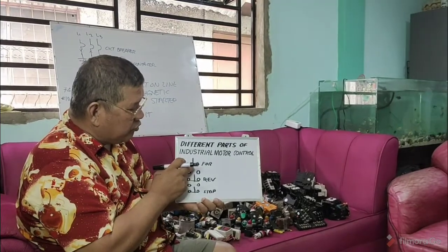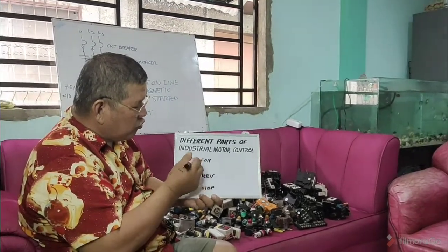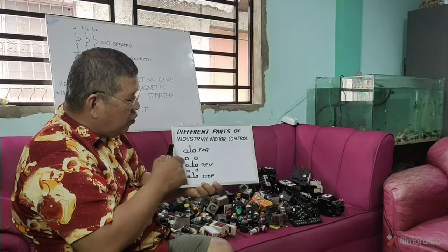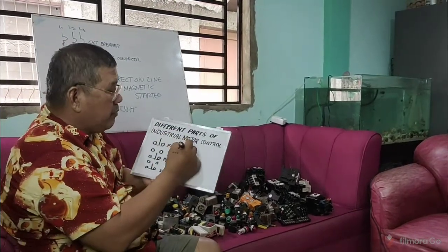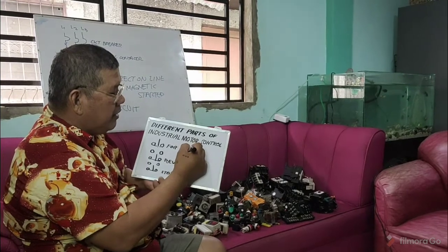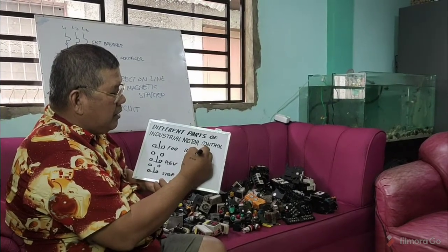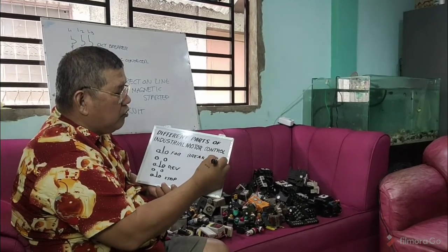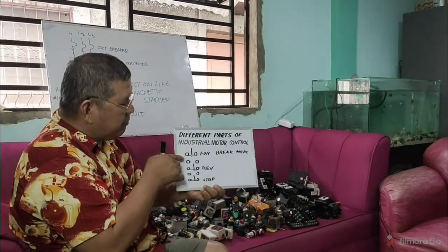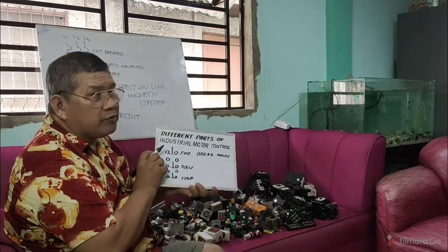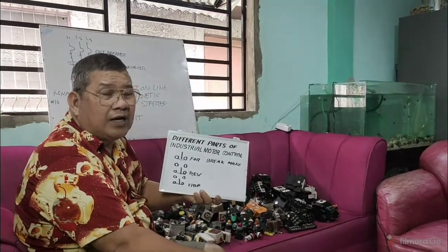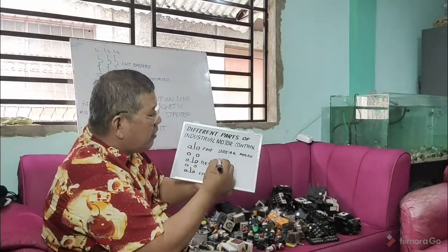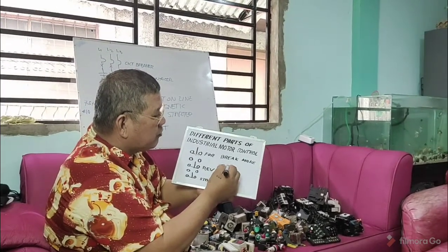When you press the button here, this one will contact the normally open, like also this one. So this is what we call a break make push button. Why is it called break make? Usually, this is called double contact. Now, why is it called break make push button? I will give you an example. For instance, this is your break make push button.